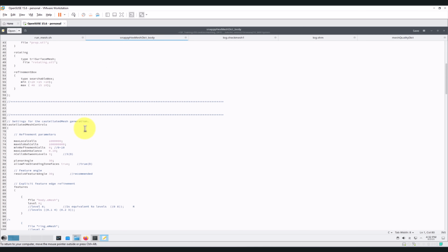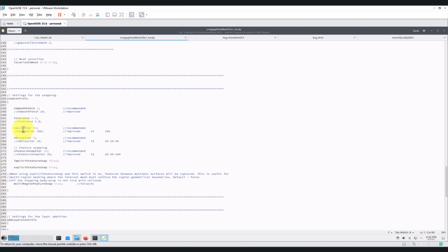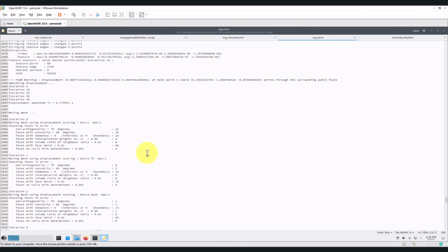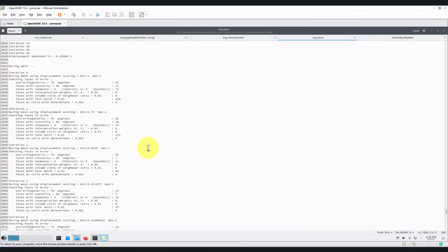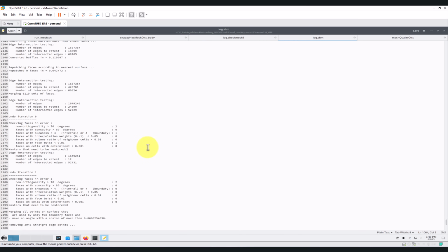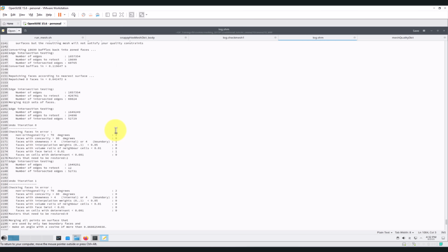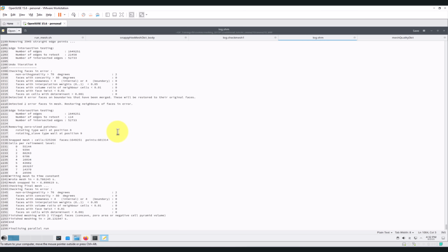So these steps that you have here, let me go here. This represents the end solve, iter, and so on. These are the iterations, but you see here it is redoing and redoing, iterating more and more, just to try to enforce your quality metrics, or until it reaches the final iteration. So as you see this, you might think it is a difficult mesh, but look at that. It didn't take too many iterations. Now, knowing what we do, remember always: the finer the background mesh, and also the finer the surface mesh, the better the result will be. So here it is. We have a good mesh.